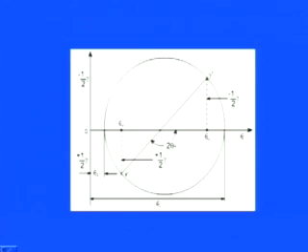These are the coordinates. Once you have these, you simply drop those vertical lines. Then on the y dash side you have the y coordinate, that is plus gamma xy by 2. On the x side you have minus gamma xy by 2. So you have the coordinates for this one, epsilon x comma gamma by 2, and this is epsilon y comma gamma by 2. And then you see the angles towards the major side, because we are always taking 2 theta. So we can say this is the 2 theta angle. These are the required parameters which you can easily measure if you simply draw the Mohr circle with the given information.